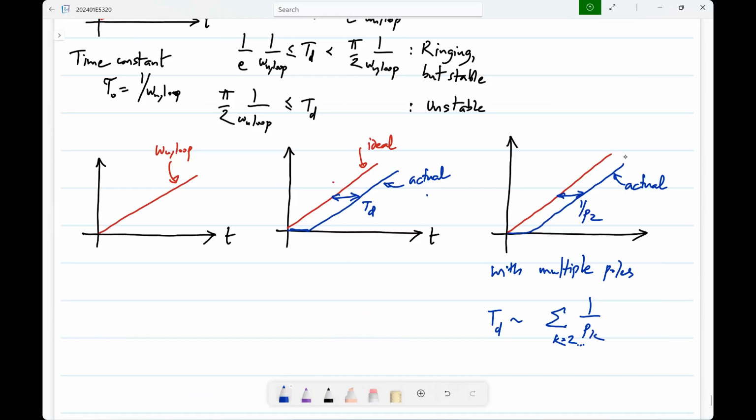Is this clear? You would have done the same things in the frequency domain, but I am showing you the time domain stuff. Is this part clear? You can tolerate a certain amount of delay in the feedback loop. If it comes from 2 poles, you can apportion some delay to each one. If it comes from 6 poles, then obviously each one must have a smaller delay. So that means the poles themselves must be at correspondingly higher frequencies, right? So maybe you can tolerate 2 poles, both of them at 1 megahertz, or four poles, each of them at 2 megahertz, and so on. They will all have the same effect on the stability and ringing and so on.